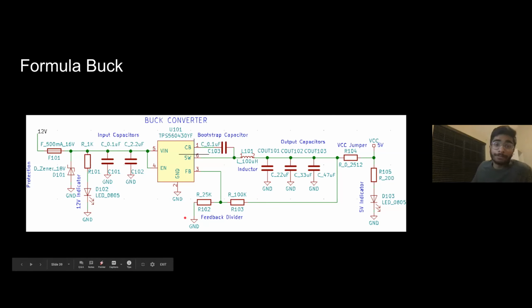It's a little bit different from what we've seen, but there's some elements that are the same. You have that LC filter, which is really the heart of the buck. You have your switch, which you can't really see here because it's inside the semiconductor. Interestingly enough, there's no diode. Don't let that confuse you. Don't worry about it. I'm just making sure y'all know that it's not there. And there's some other bits and pieces, but you have your output capacitors, input capacitors. We're taking 12 volts and we end up with 5 volts. Cool.